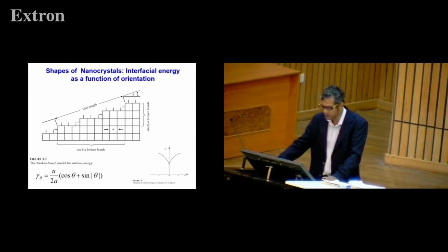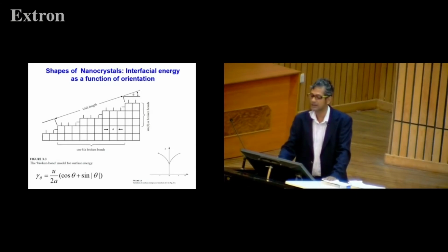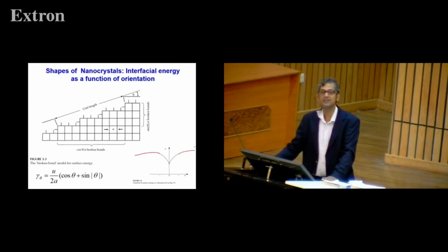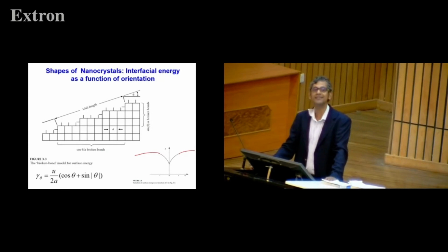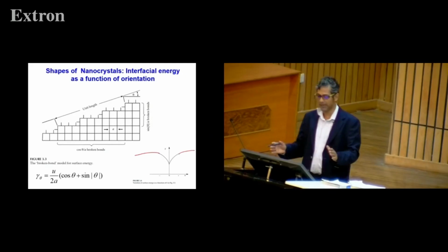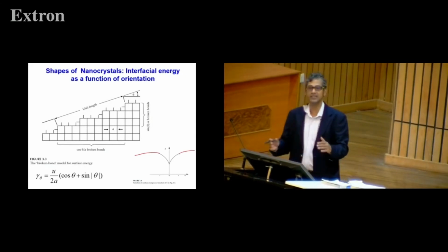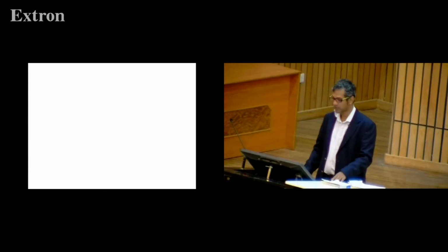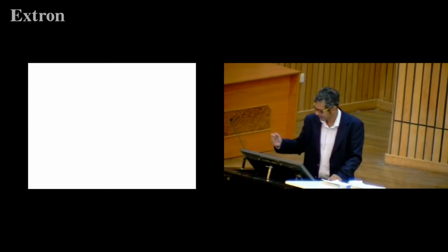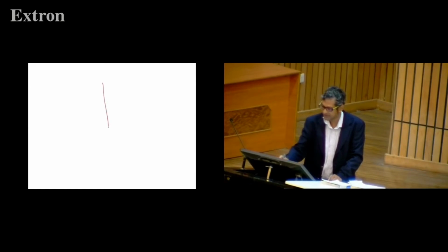And interfacial energy does change as a function of theta, like this, right? And the minimum is at the closest packed plane like the 111 plane in FCC structure. As you go away from that, the interfacial energy increases rapidly. So that means we can create an interfacial energy versus theta plot. We can always create that, and I'm going to do it for you before I move into other topics.